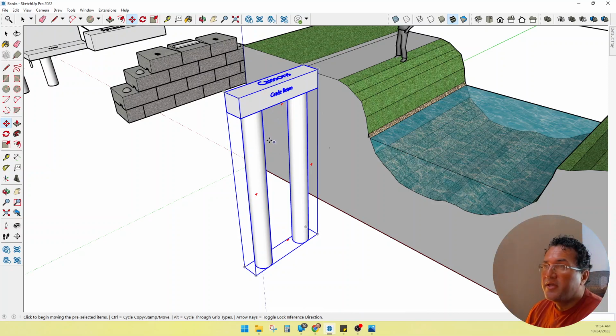Okay, that's caissons. Sometimes there's only 2 caissons. Sometimes there's 4. Sometimes there's 6 per abutment. It really varies on your site. The depth of the caisson varies as well.